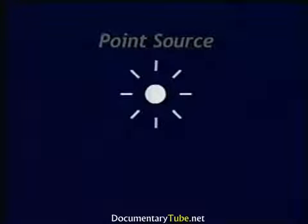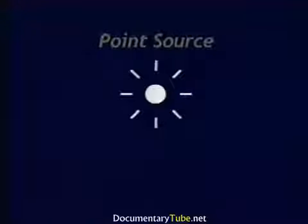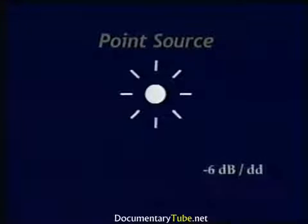Let's first talk about the sound source. We'll describe two basic sound source types and the relationship to highway traffic noise. A point source is defined as a source that's essentially concentrated at a single point from which noise propagates outward in all directions. In other words, sound radiates spherically from a point source. The sound levels measured from a point source decrease at a rate of 6 dB per doubling of distance. This is a decrease due to spherical spreading.